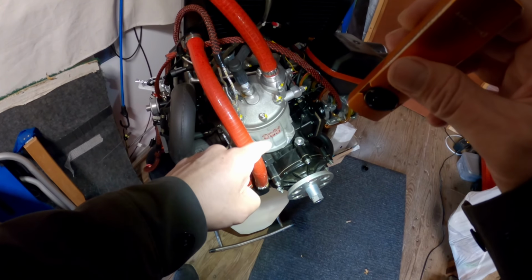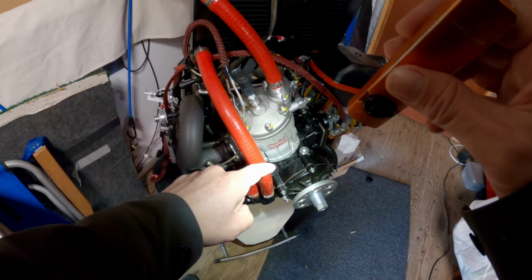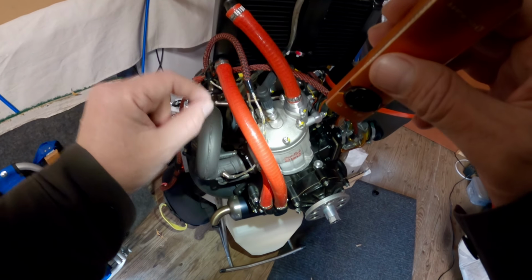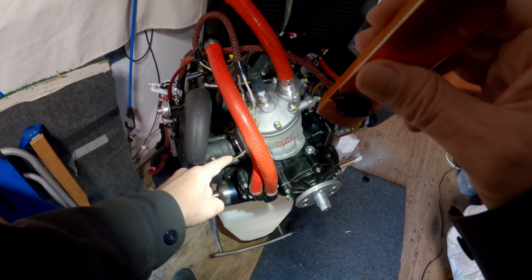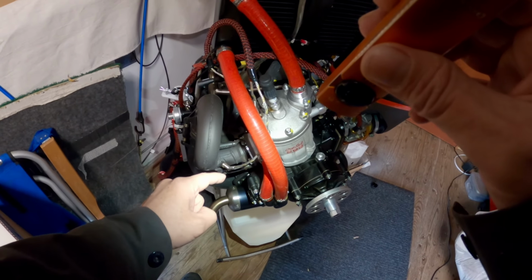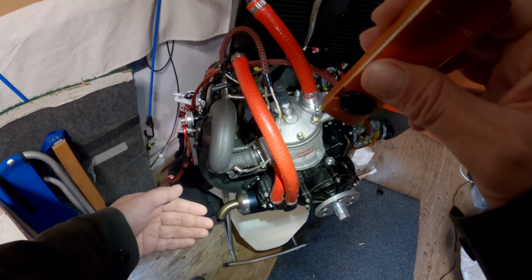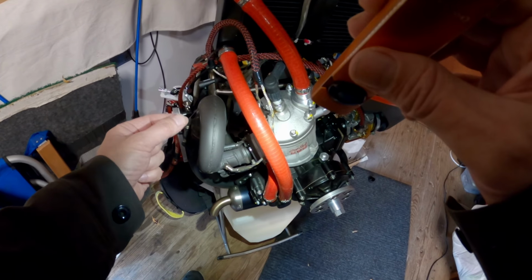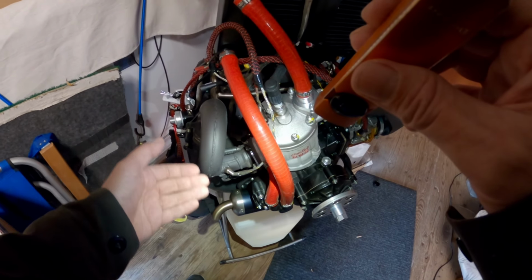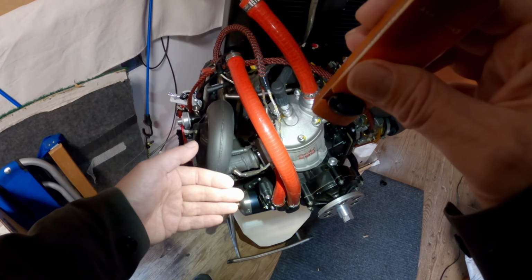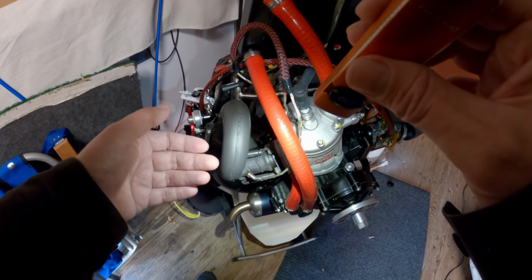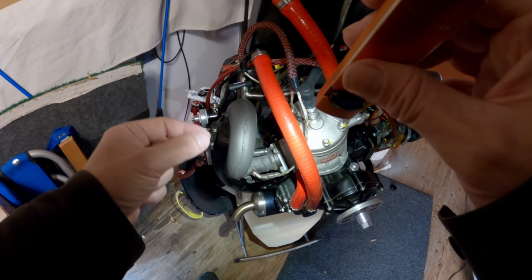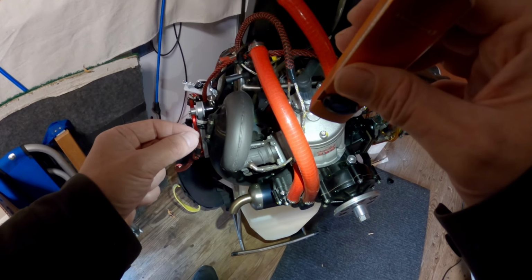That means the 303 does not count. There might be a slight variation. I have not tested it. I know this engine and what optimal EGTs are, which also correlate with manufacturer suggested EGTs for cruise RPMs and wide open throttle, and that has been triple, quadruple, however many times verified by other pilots with their independent testing.